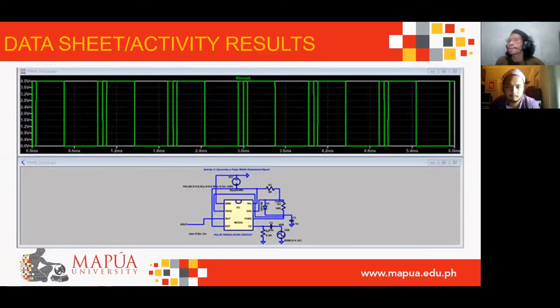You can see here that the PWM signal is generated with a duty cycle of around 80% for the first positive or the high state. Then for the corresponding negative cycle of the modulating signal, the pulse is on low state.